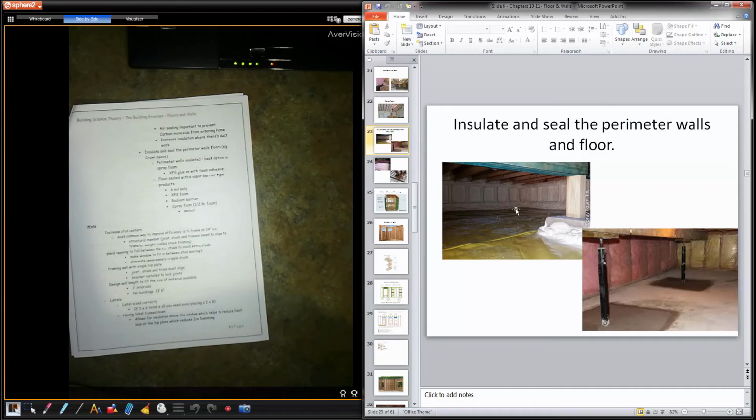As you're crawling around, your knee's going to crack the foam because it's not perfectly level. By spray foaming a thin layer on the entire bottom surface, that won't happen. Right? Doesn't look as pretty, probably cost you a little bit more money, but you're going to spend quite a bit of money on the XPS sheathing to cover this entire floor. But as you crawl around under there, you're going to break little pieces off, and then it's just not as good. That piece gets shifted, it's losing some of the R value. So spray foam under this area would probably be the best, on the floor and on the walls.